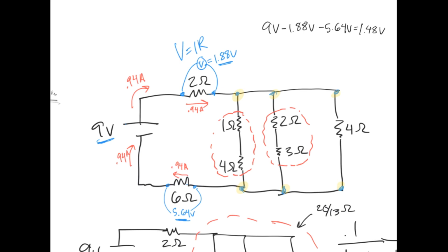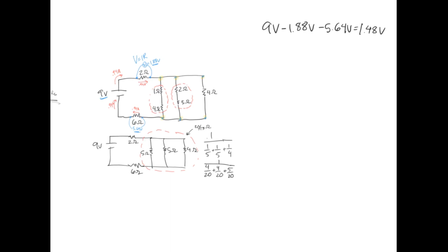Now that I have the voltage across each of those, and I have the resistance, like there'd be 5 ohms in this line, 5 ohms in this line, 4 ohms in this line, I can use Ohm's law to solve for how that current gets split up in all 3 of these. You wouldn't be able to eyeball how much current and voltage is across each of these devices, but you can do that with circuit reduction. That process involves first identifying all your series connections, then reducing your parallel connections, and then working your way around the circuit using Ohm's law to solve for different values.